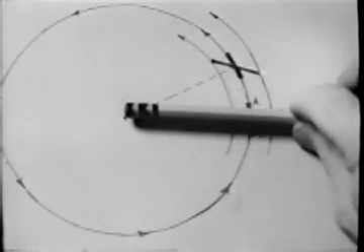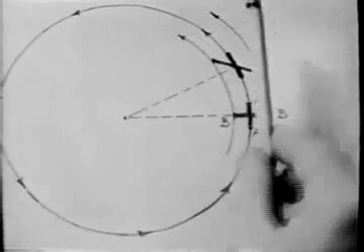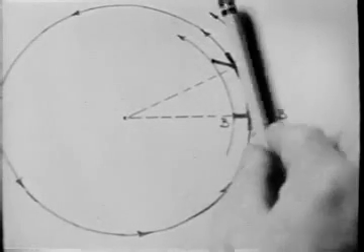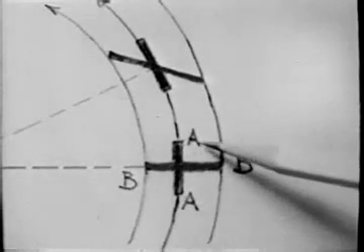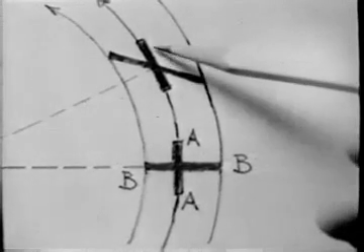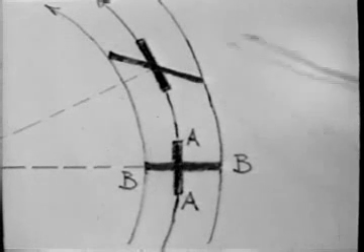The clockwise turning rate of B is just equal and opposite to the counterclockwise turning rate of A, and so the net vorticity is 0, and the vorticity float confirms this. Incidentally, since the two vanes of the float are rigidly connected, the float does not respond to the shear deformation of the two fluid lines, but only to their average angular velocity.